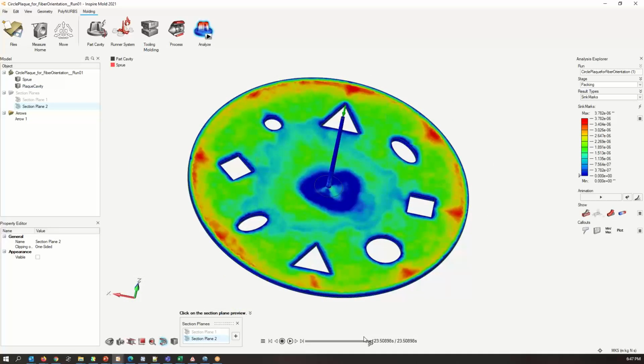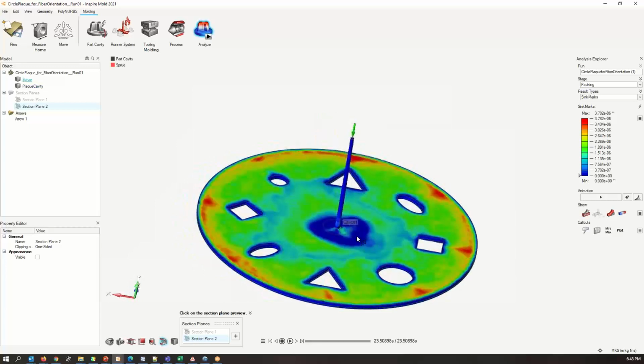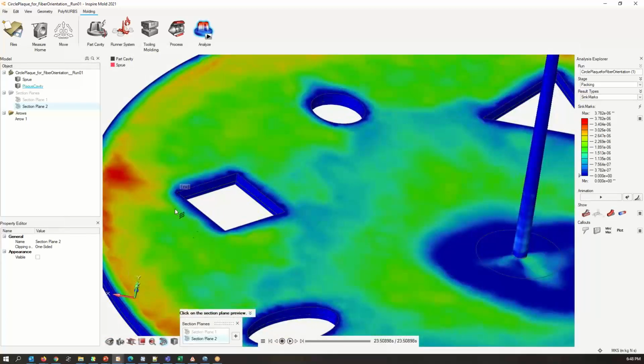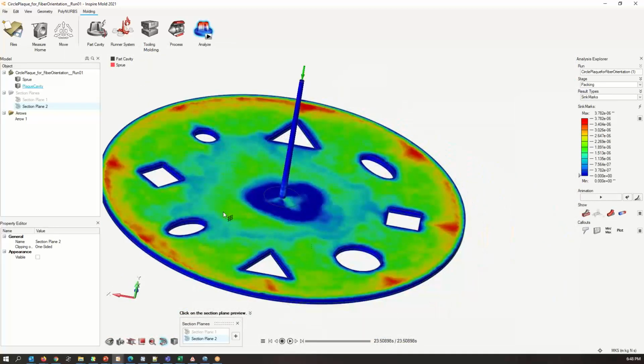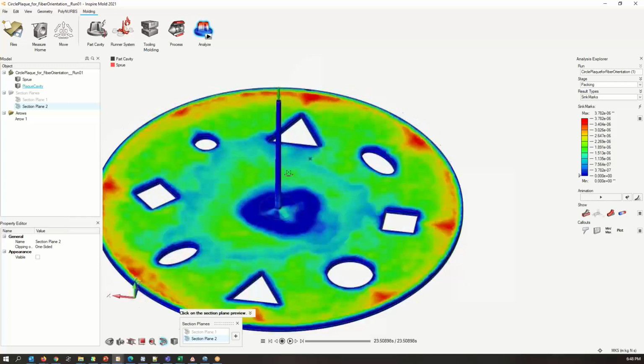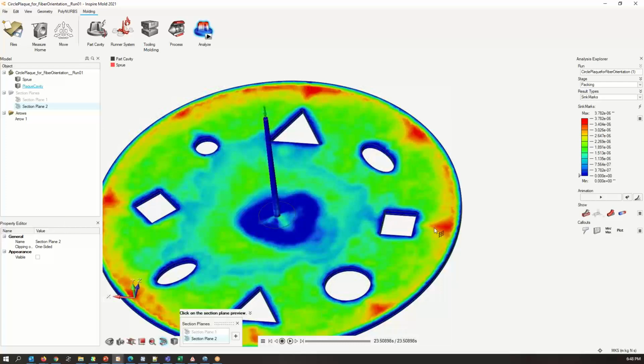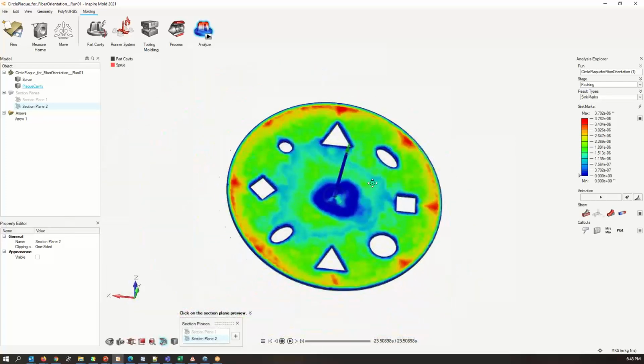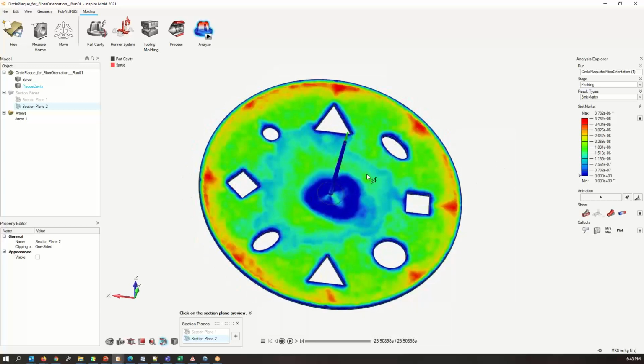Same basic idea, right? I'm going to freeze really close to it, then I'm going to freeze top and bottom out here. But here I had this extra shear face as I was coming out to it and finishing filling. So I had that flow front coming out, and then it kind of hits the end, and so I have that edge effect happening there. These aren't really long enough to have that, but we'll look at that in terms of the knit lines that form. You can also see some extra heating where the knit lines are forming as it comes around. Out here as well. So where those knit lines are forming, it's going to shrink just a little bit more in those places.